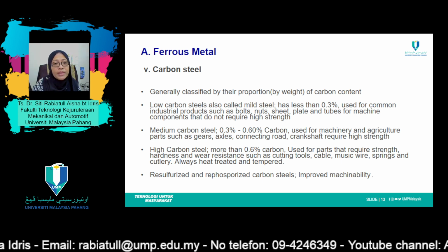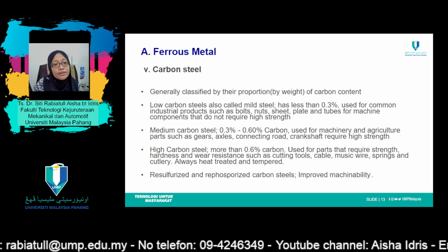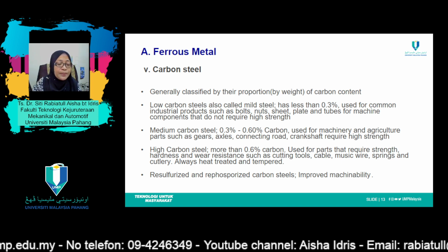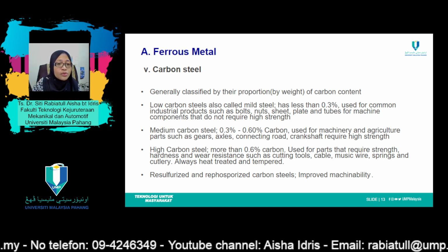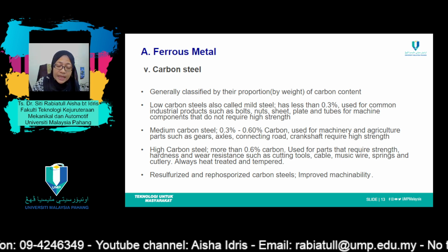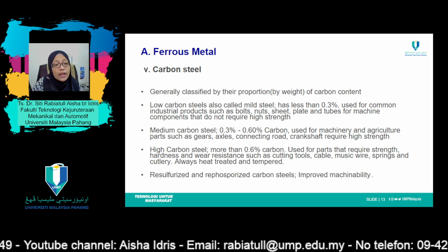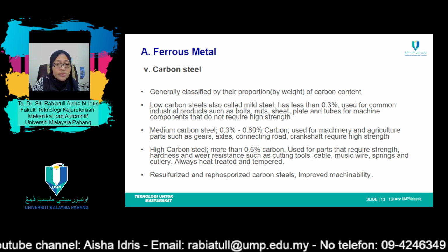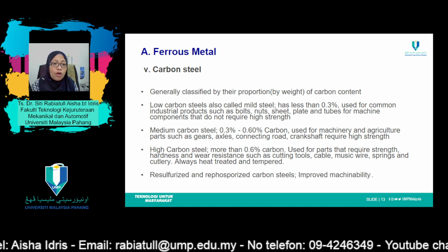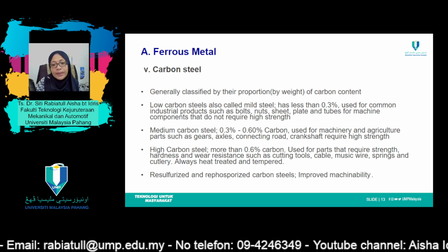Additions of chromium, nickel, and molybdenum can improve the capacity of this alloy to be heat treated, giving rise to a variety of strength-ductility combinations. These heat-treated alloys are stronger than the low-carbon steel but at a sacrifice of ductility and toughness. Applications include railway wheels and tracks, gears, crankshafts, and other machine parts, and high-strength structural components calling for a combination of high strength, wear resistance, as well as toughness.